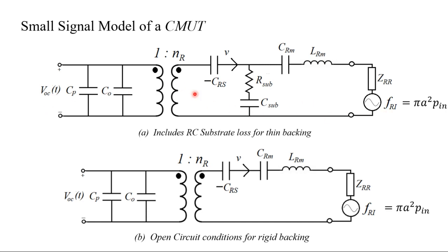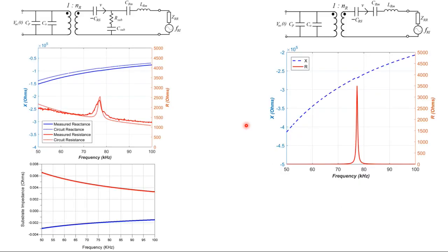For receivers, you have a linear small signal model, and the force is linearized. So this electromechanical turns ratio and the spring softening capacitance handle that force. Over here, if you calculate from this node down to this node, the voltage across this shunt branch is the transduction force. That's what the transduction force is for the linear receivers. So the difference between these two models is explained over here.